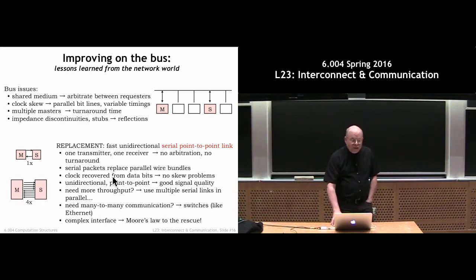If I need many of them, I know we're going to put many of those things in parallel. So PCIe times 2, times 4, times 8, times 16. You buy a high-end graphics card, right? It's a PCIe times 8 or something. And what that means is that the communication between the CPU and the graphics card is over 8 independent multi-gigabit per second serial channels.